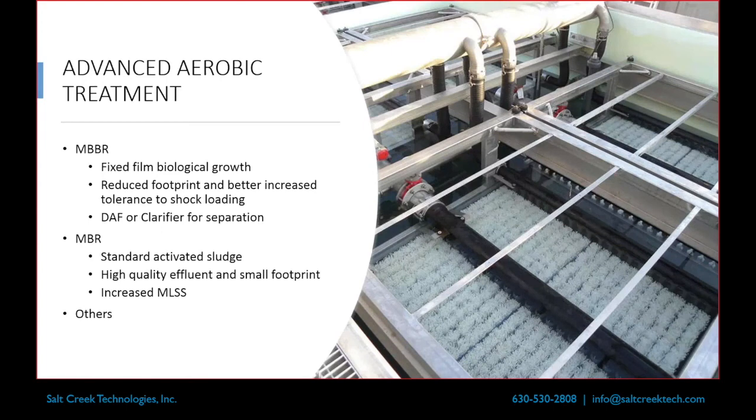So we've already talked a lot about the activated sludge systems and conventional systems. Figured it'd be worthwhile just touching quickly on more advanced systems that have been getting used more frequently recently. They're MBBRs, which is a moving bed bioreactor. I call it bug condos, and that's a really great name. They're essentially like Lego pieces that let the biological material build up on that plastic. And so it's actually a fixed film biological growth rather than a suspended growth biology.